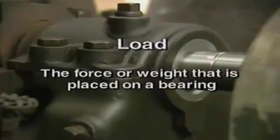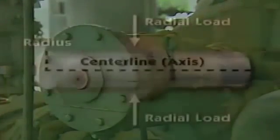The term load refers to the force or weight that is placed on a bearing. Different bearings are designed to withstand different types of loads. Most sliding surface bearings are mounted on rotating shafts, and the type of load that is placed on the bearing is determined by the direction in which force is applied in relation to the shaft. In these terms, load can be either axial or radial.